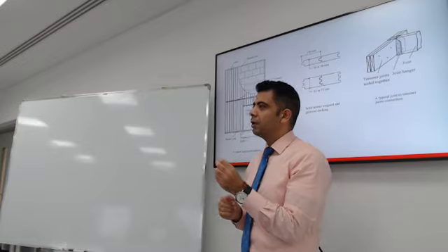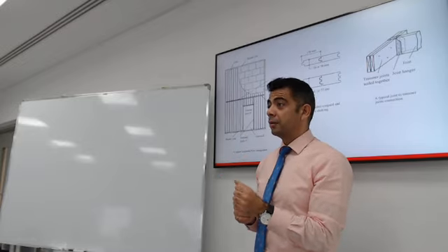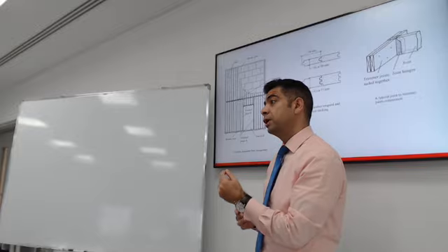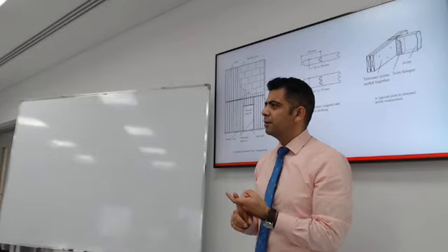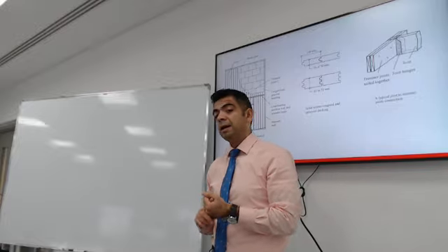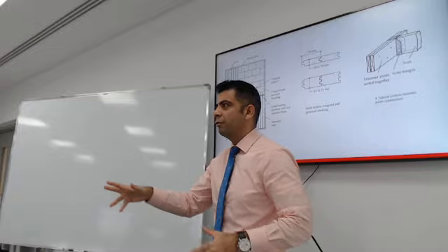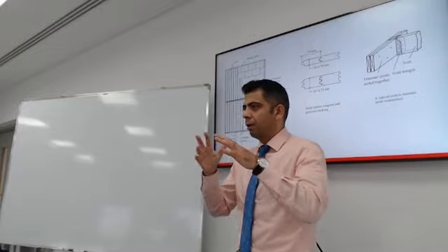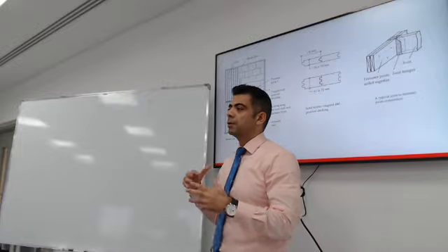It's a different way of building. If you're not used to living in a house made out of wood, the sound isolation is not the best. You need to pay attention to moisture. It's not going to be very water friendly if you have a bathroom with leaking faucets and leaking taps. This all has to be taken into account when you're building with wood.